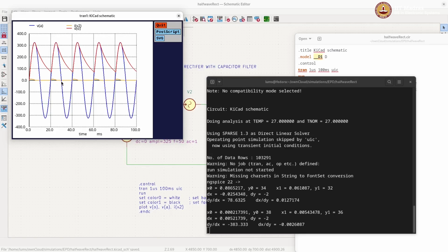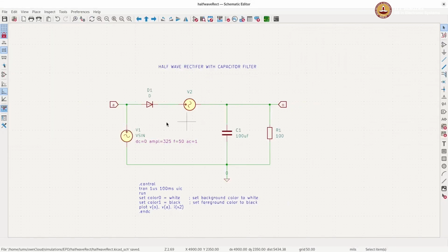So these current waves. So in this way you can actually visualize the voltages and the currents of any part of the circuit through simulation, get an insight, understand about the circuit, and try to design the same. Now I would recommend that when you are placing the components, you use generic components, because you may not know the ratings. Only after you have completed the simulation, probably, you can look at the waveforms and then come up with more precise ratings for the diodes.